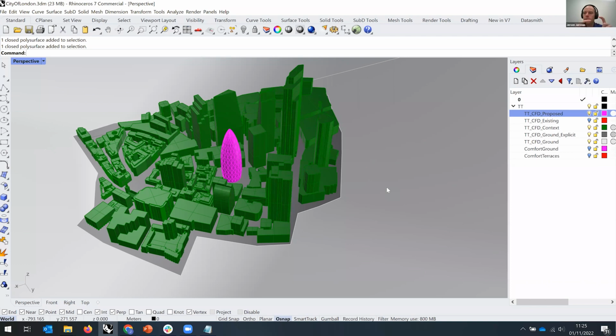So you can put in both. You can put in your 4-story building. You can put in your 100-meter tall tower, your 20-story, 30-story building. And the digital wind tunnel, and therefore the size of the mesh and the resolution, as well as how the results look, etc., is calculated on both. So it's basically calculated on the worst, the tallest building of both. And then in the app, you can choose, I want to run a proposed, I want to run an existing.